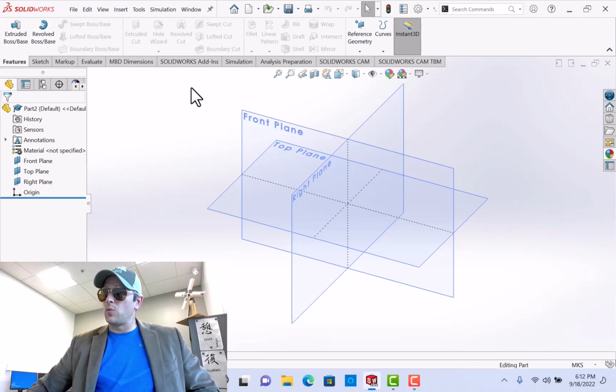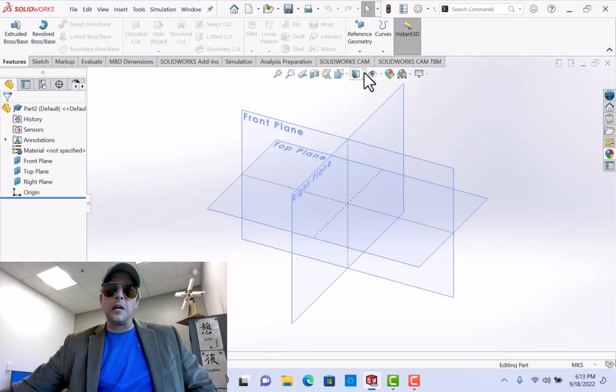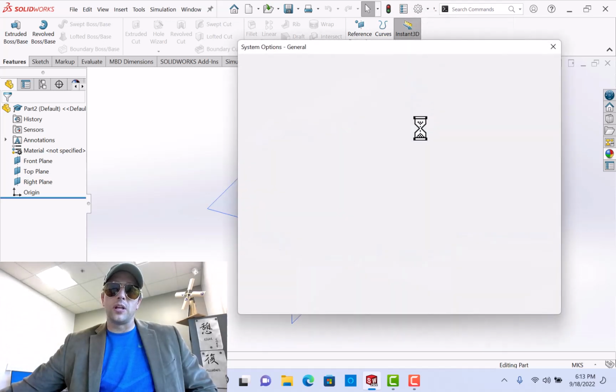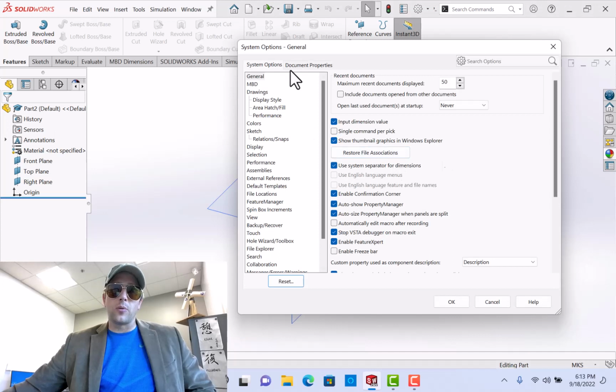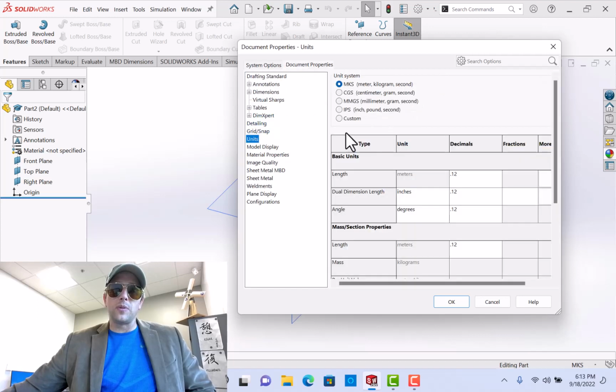We just started on 6.1. You can see the dimensions for the gasket at the very start. All dimensions are in millimeters. So the first thing we always have to do in every part is define our units. There's a reason why we define our units at the very beginning. One is so that it's consistent all the way through, so we don't have a jumble of different units. Also, if you're using the wrong units and then you convert, it will keep the same values, but it will not convert them.